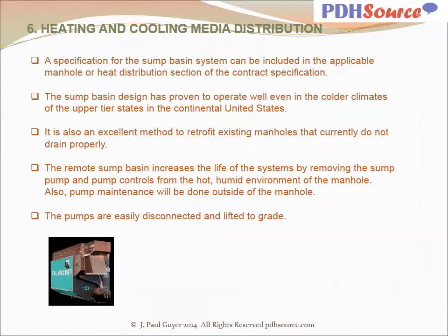A specification for the sump basin system can be included in the applicable manhole or heat distribution section of the contract specifications. The sump basin design has proven to operate well even in the colder climates of the upper tier states in the continental United States. It is also an excellent method to retrofit existing manholes that currently do not drain properly.